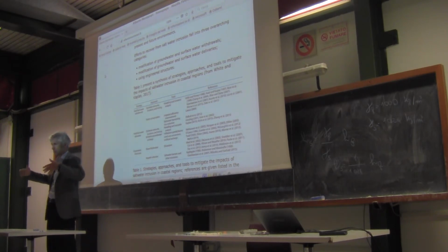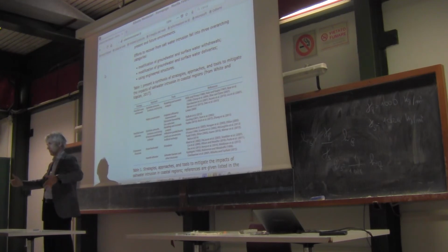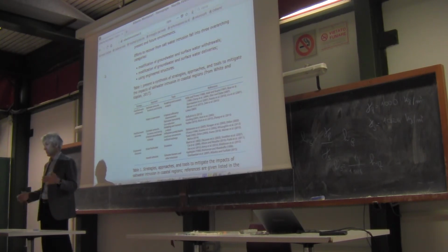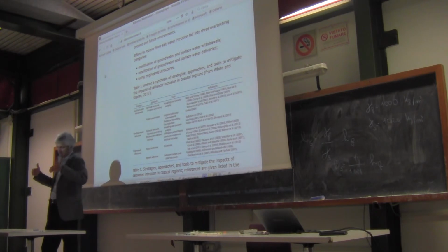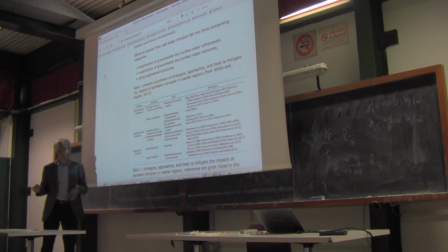Do you understand what a sheet pile is? It's like a wall that you put into the soil. It's a barrier that can be made of metal or concrete to artificially construct an impermeable layer. So if you build a sheet pile and go deep underground, and it's possible because sheet piles potentially can reach very considerable depths, of course you create an impermeable layer and you stop saltwater intrusion. And the question is how deep should we go, which is a relevant question, of course.